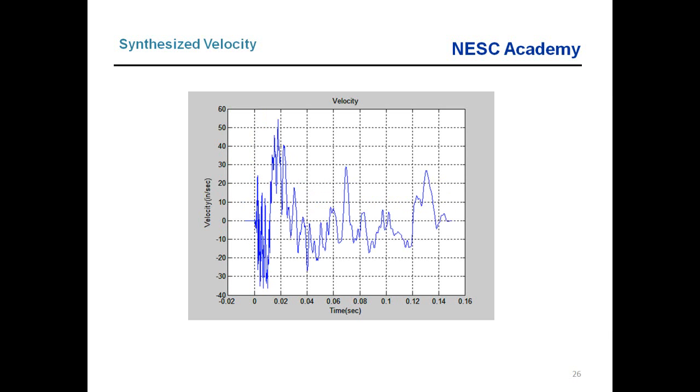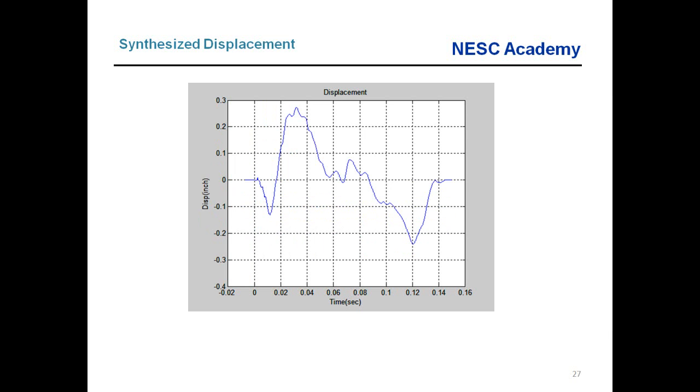And here's the corresponding velocity. The corresponding velocity is stable, and it ends at zero. A bit of an oscillation about the zero baseline. Displacements can sometimes be a bit one-sided. This one almost looks like an N wave, like for an aerodynamic shock pressure. In other words, a sonic boom. That's just by coincidence. But this is a stable displacement. It's less than 0.3 of an inch, and it has a net value of zero. So that's a pretty good looking displacement time history there.